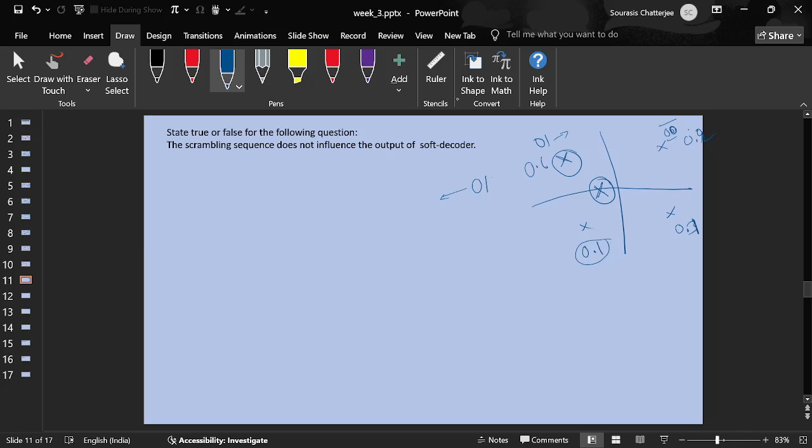And it is seen that when you do soft decoding compared to hard decoding, you observe, let's say in dB terms, almost a 3 dB gain. You know that 3 dB corresponds to a multiplicative factor of 2. So that means the user can be at twice the distance in case of soft decoding compared to hard decoding, and still obtain the same SNR.